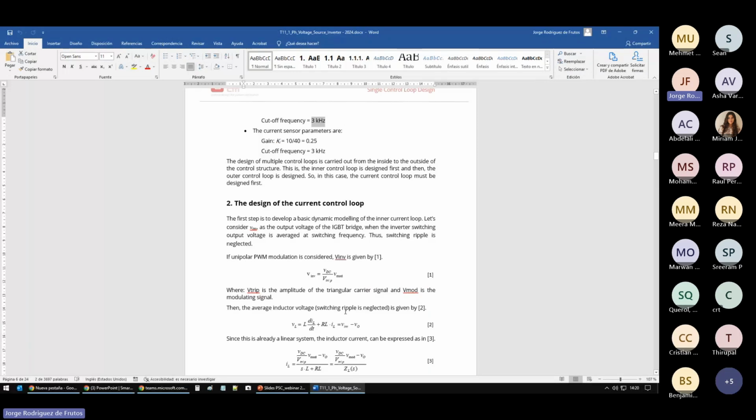So now it comes to the mathematical modeling. The mathematical modeling is performed twice, for the inner current loop and also for the outer voltage loop. In both cases, a feed-forward technique is applied. The feed-forward technique is based on adding an additional transfer function in order to neutralize several elements in our control diagram that we want to remove, so the equivalent plant is made simpler and easier.